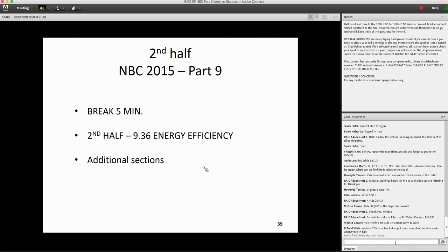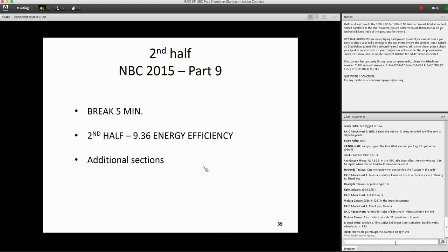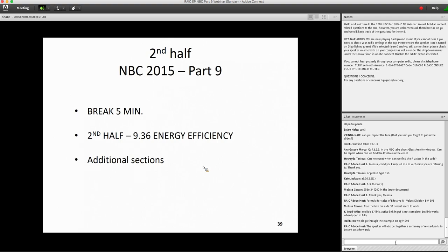So to calculate the whole assembly, do you multiply or add? Multiply. Because for the calculation, conductivity divided by thickness equals U value, but then you said the R value is the inverse. So if you divide, you get the U value. Then if you invert it again, you get the R value. So you could just multiply it. The R value. Does this show any bad insulation or anything?